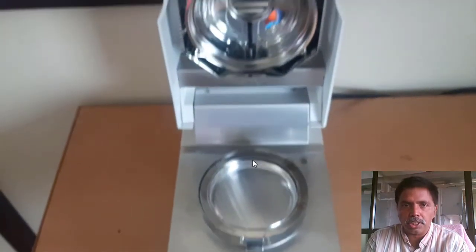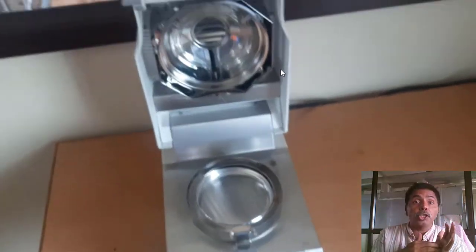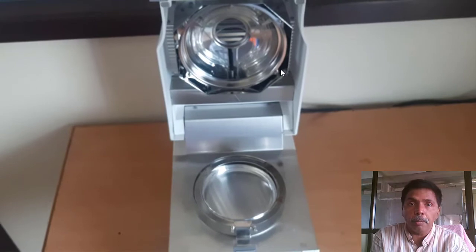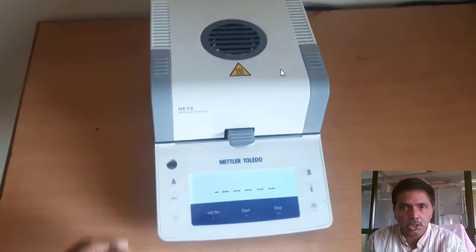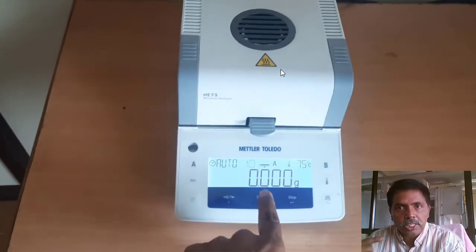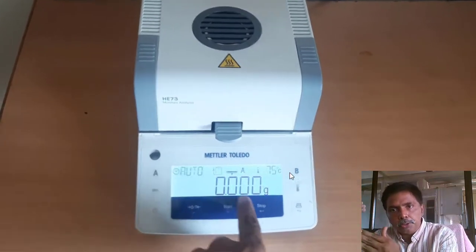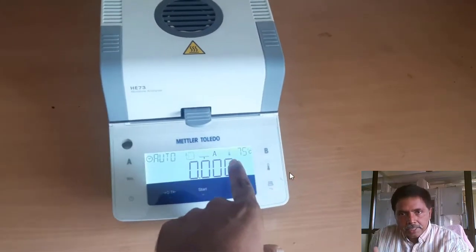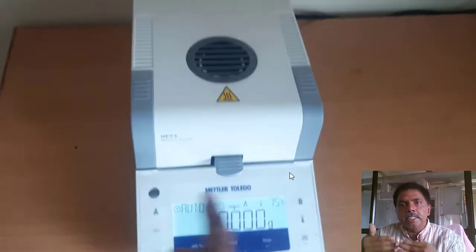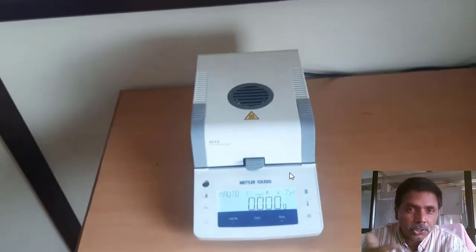This is the moisture analyzer. This is the heating coil, and we measure the evaporation rate of the moisture at laboratory level. A sample of maybe 10 grams or 20 grams is collected, and for that sample we analyze the moisture. First, how much moisture is there, and at which temperatures what the evaporation rate is. We set the highest temperature at 75 degrees and keep reducing: what is the evaporation rate, how much time it is taking, at 70 degrees, 65 degrees, 60 degrees, 45 degrees, like that. We measure the evaporation rate at different temperatures.